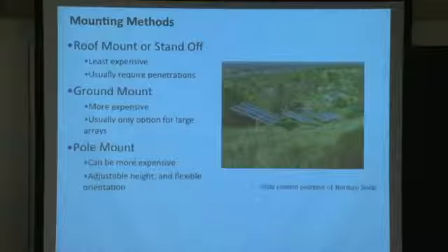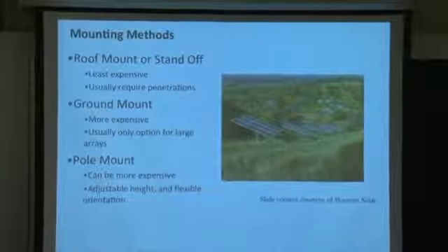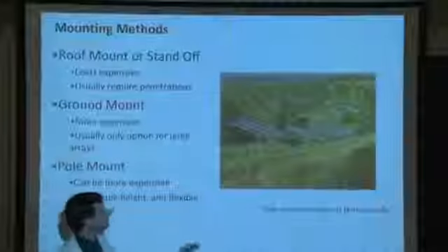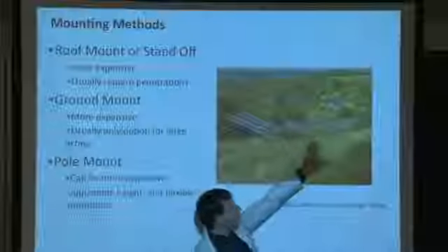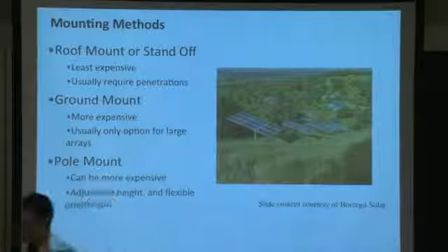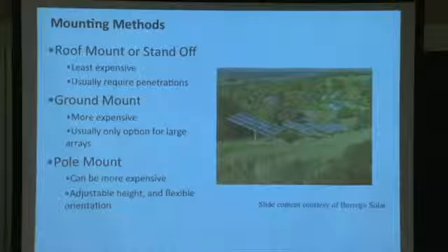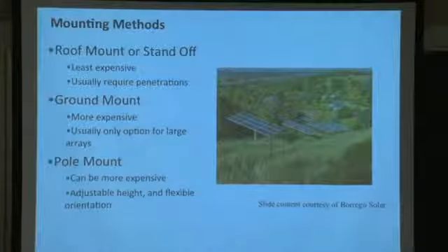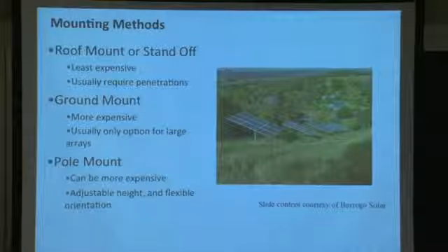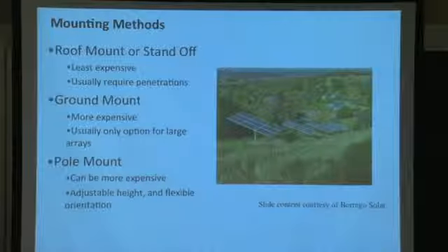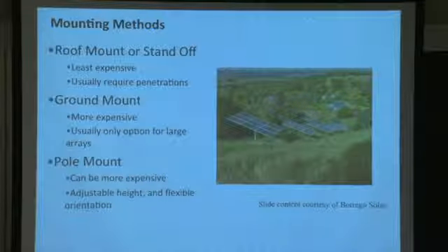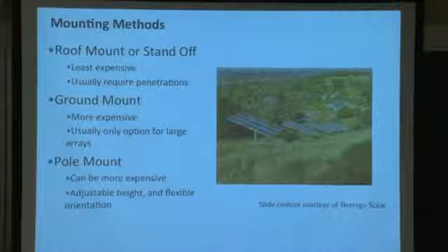And the mounting methods, we talked about mounting and racking. This type was fairly common in the early days of solar. We had these field installations, especially built on hills in California. I would say most common now is really just mounting directly on a roof, oftentimes flat. For large field installations, one-axis trackers are very common nowadays, tracking as a function of time of day, and then manually adjusting the entire array for season if need be.